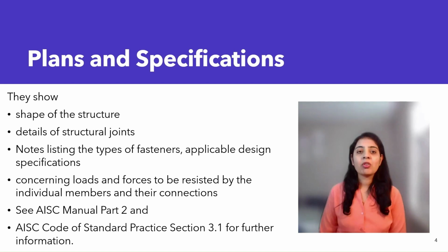Also, details of structural joints, bearing stiffeners on beams and girders, beam web reinforcement, openings for other trades, connections between the curtain wall and the supporting frame, column stiffeners, column web doubler plates, column anchorage and column splices are given.